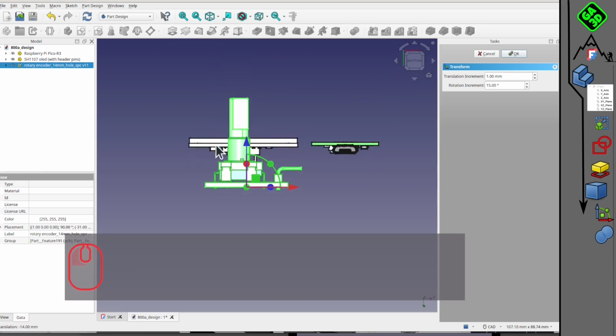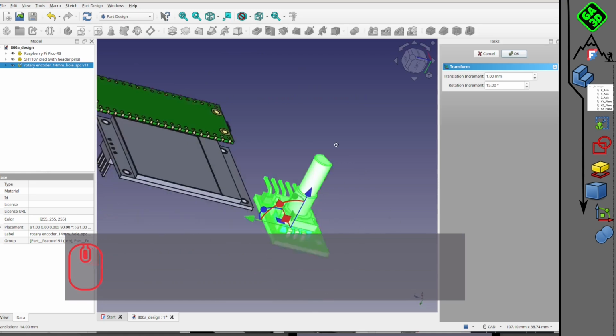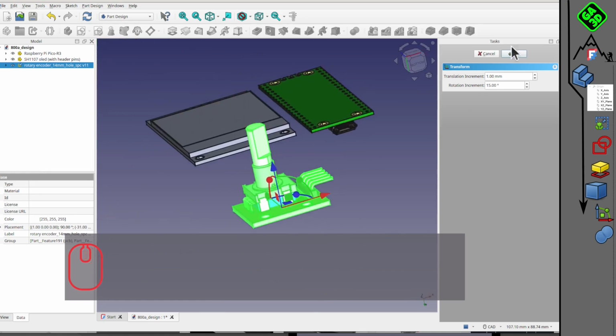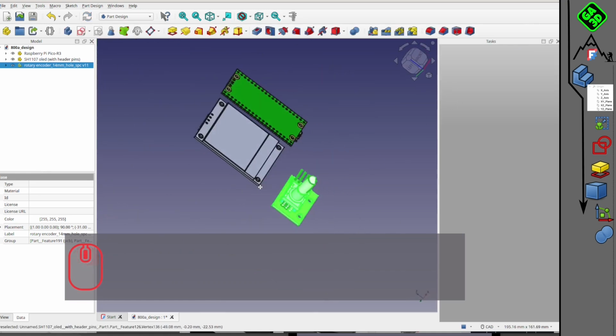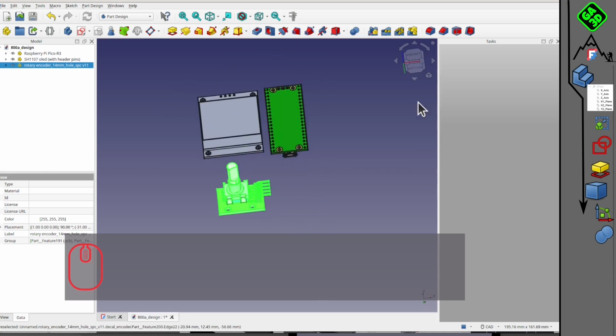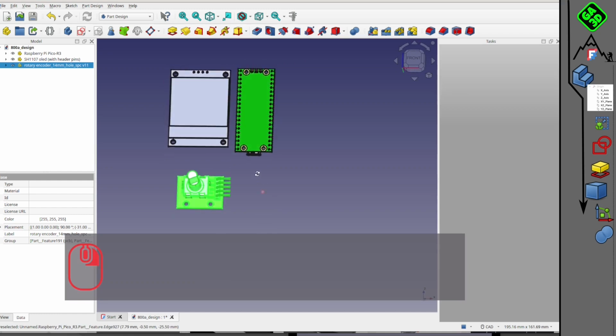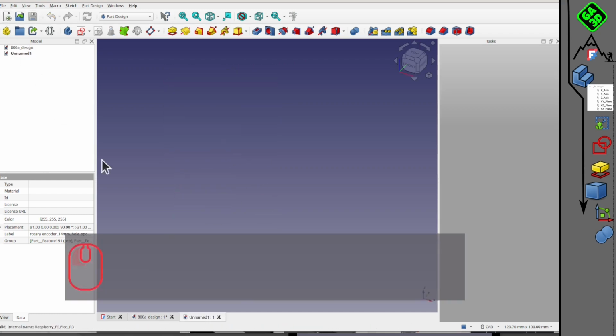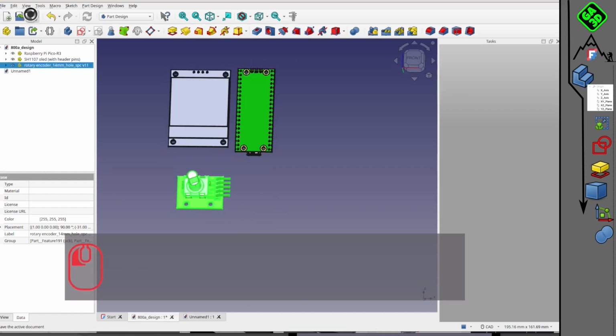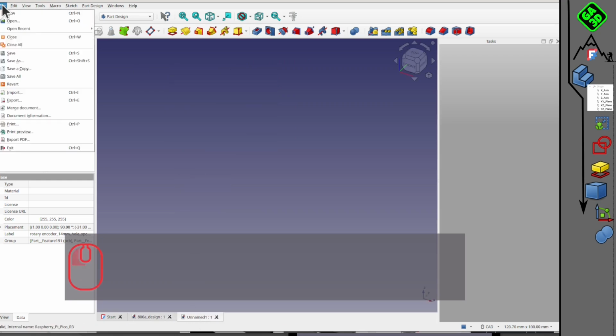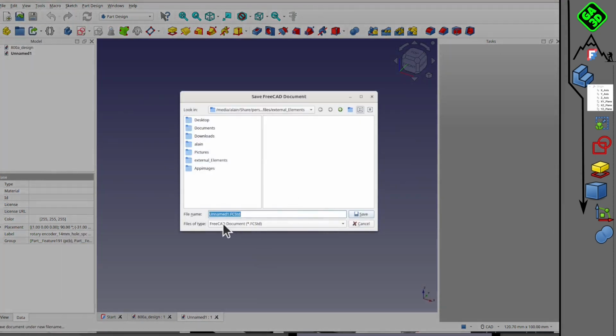So here, we're going to do something very simple. Actually, I constrain my three electronic components in the same plane. So I'm just going to select that surface there with this one, and then after that, I say here, that coincides with it.